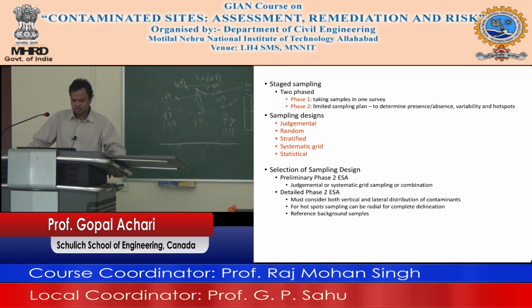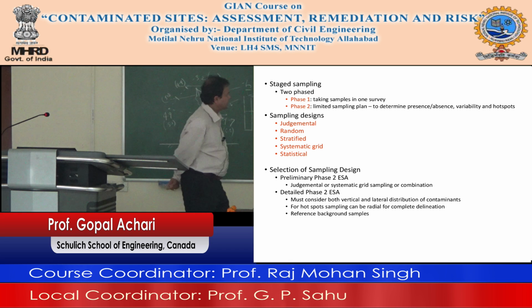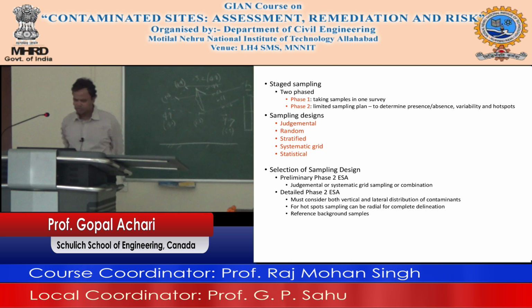Decontamination procedures to prevent cross-contamination. And I was talking about this earlier, the sampling equipment to remove organics. We have to use a methanol wash on the drilling and other equipment. You have to make sure they are decontaminated, so you are not doing any cross-contamination between samples.